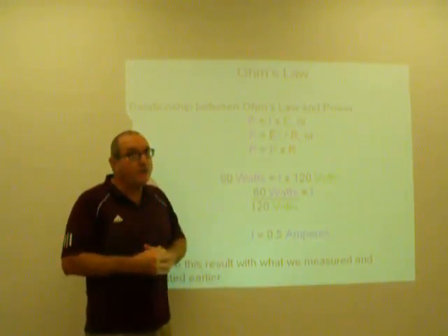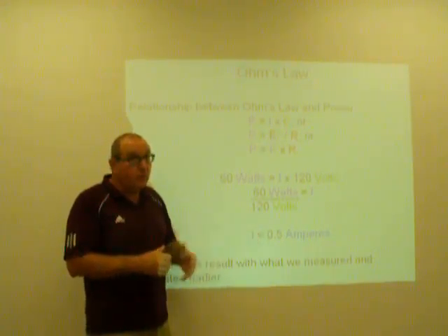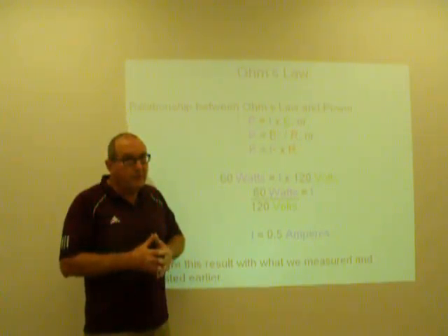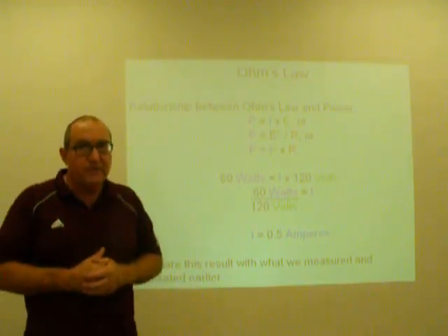That's what we measured. So obviously our measurement of the resistance of that filament cannot be accurately made, because as the calculation showed earlier, the resistance of the filament when it's operating at full operating temperature should be somewhere around 240 ohms, not 20 ohms. But you can certainly go through those equations yourself.